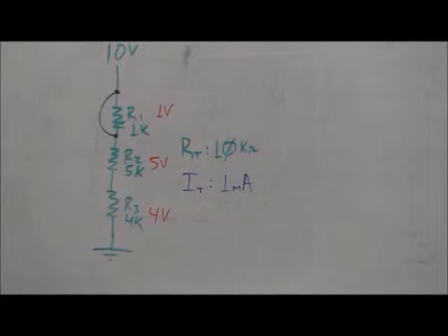Okay. If we shorted around R1, what happens to the total resistance? Goes down. It decreases, right? Because we remember the rule, which told us that if any branch resistance increases, total resistance increases. If any branch resistance decreases, the total resistance decreases. Yes?